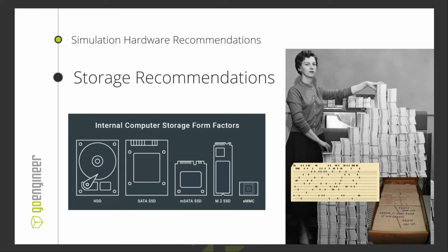What that does is it gives us the benefit of letting Windows do its thing on one hard drive, and we don't have to wait for Windows. If it decides it needs to write something in the background, we can continue on with our SolidWorks simulation work. And this is key. The SSDs that we're using today are super fast. When we're doing analysis, there's a lot of data being written to your hard drive in the middle of the analysis, so you want really fast solid state drives. These are almost on par with the fastest RAM you can put into your system, but they're not nearly as fast as your CPU. Your CPU is the fastest component in your system, hands down.